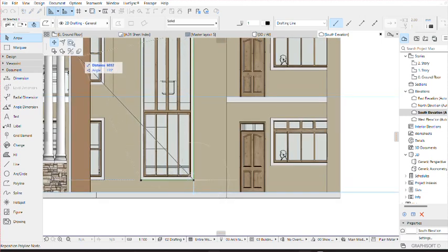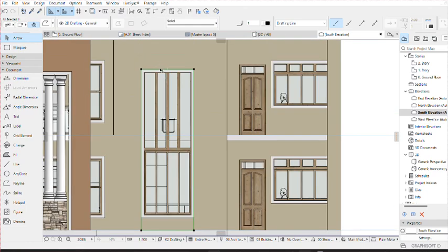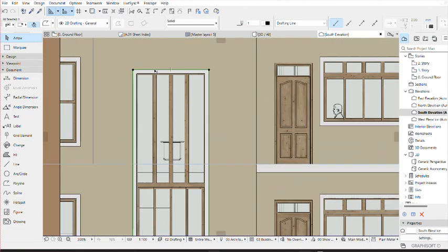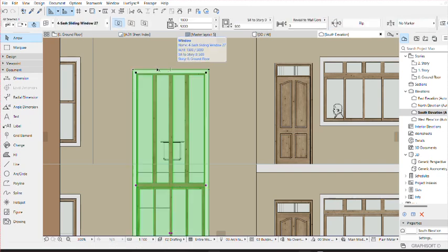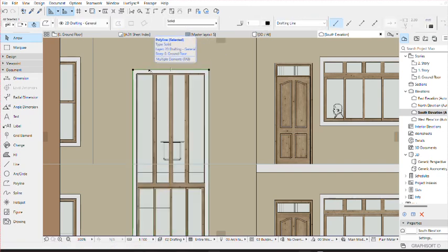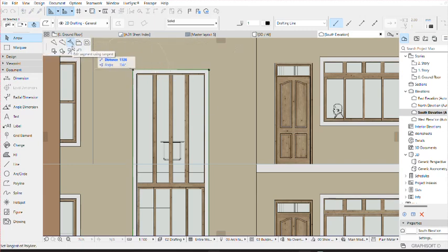Later on, I can use the morph tool to produce my design for this window. I want this design to have some arch up here. So this is the line I've just drawn. I make sure I edit this segment into an arch, maybe at an angle of 45.